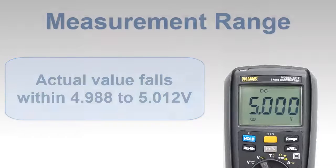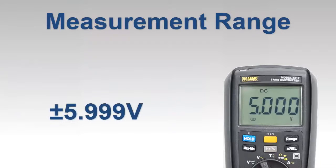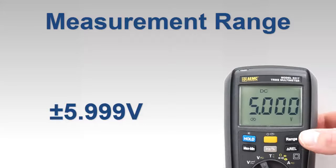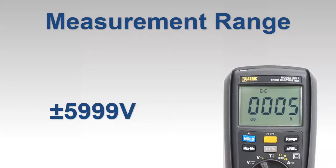This calculation highlights the importance of selecting the optimal measurement range. To demonstrate this point, watch what happens as we change the multimeter's range to plus or minus 59.99, 599.9, and finally 5,999 volts. Notice the decimal point moves to the right with each change of range. This indicates an order of magnitude increase in a least significant digit, and as a result, a commensurate increase in the value of 1 count.